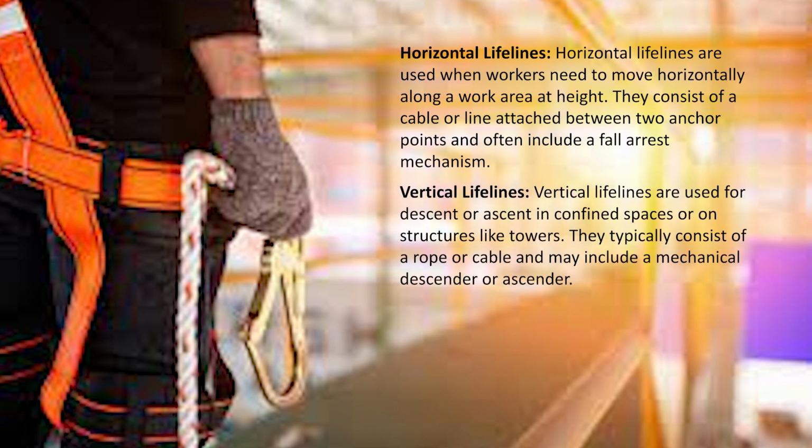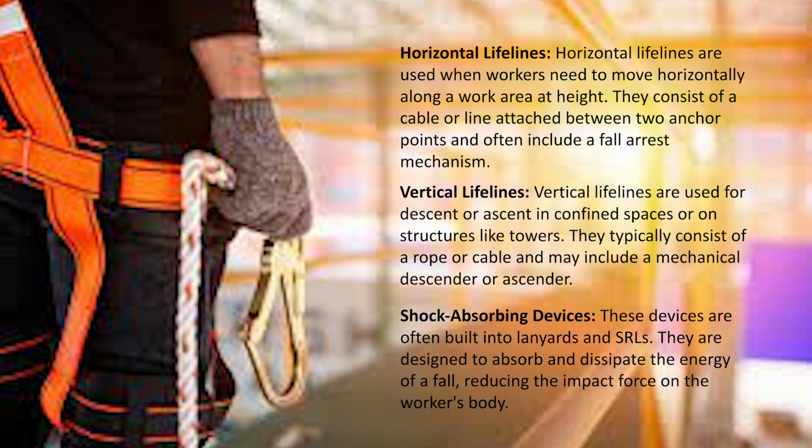Vertical lifeline. Vertical lifelines are used for descent or ascent in confined space or on a structure like a tower. They typically consist of a rope or cable and may include mechanical descenders or ascenders. Shock absorbing device. These devices are often built into lanyards or SRLs. They are designed to absorb and dissipate the energy of a fall and reduce the impact force on the worker's body.